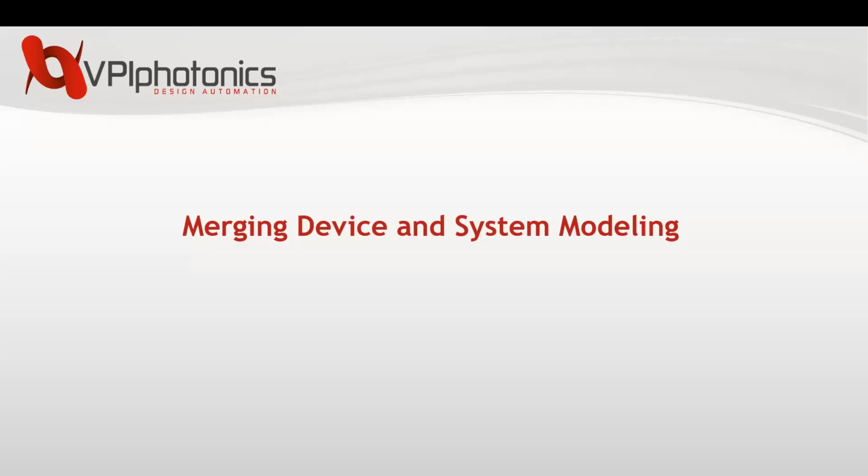Well, you have this modulator that has all of, let's say, the bias dependence and lots of other geometric parameters that need to be optimized for it in the design. So you have this complex device that Eugene talked about, and now you want to put it into a system that has, let's say, even optical fiber in it. And the optical fiber is going to have linear distortions, linear impairments, but more complicated, it's going to have a lot of nonlinear characteristics to it as well. And so taking your device and putting it into a real system allows you to really look at how it's going to work with fiber or other components in the network, as well as any DSP that you may have added on top of that.